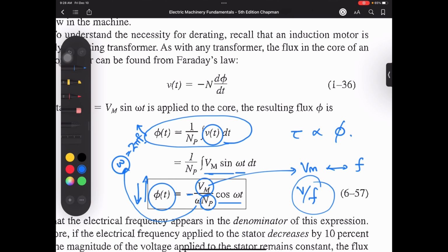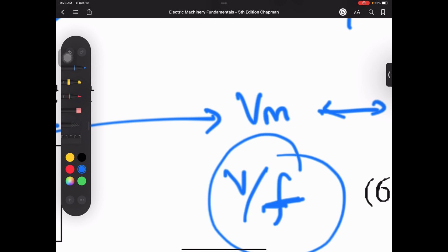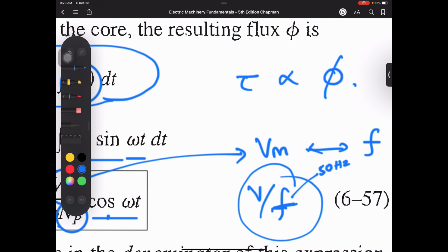And one thing very important, here is another very important thing: if you are increasing your frequency, okay, suppose I had a machine design that was designed for 50 hertz. I say no, I am now going to give it a very high speed. I want my synchronous speed to come in some thousands, 10,000, 14,000, something like that. I increase my frequency from a variable frequency drive to approximately 400 hertz, 8 times increase, which means my NS will become, it was supposedly a 2-pole machine, from 3,000 to 24,000, 8 times increase.